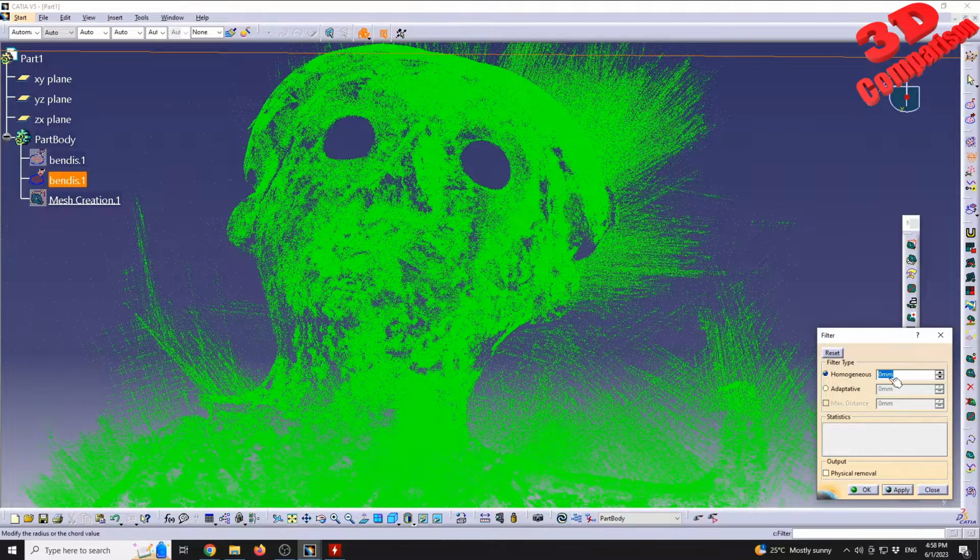So I'm gonna go with 2 millimeters, not adaptive. This should also process quite fast. And I'm gonna create the mesh again for that one. Also, the main advantage of using filtering is that the noise level will be lower, since the sampling points will be at a fair distance.